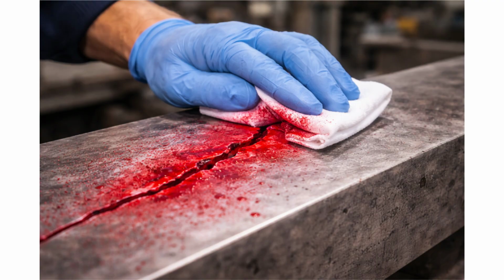Solvent removable. The dye penetrant solvent removable method is most popular because it is low cost and very versatile. You use a clean cloth lightly dampened with solvent to wipe away excess penetrant. The key technique for solvent removal is to use a clean cloth for each wipe. You are not trying to scrub the surface clean, you're gently removing the excess while leaving the penetrant in the cracks undisturbed. If you are too aggressive, you'll pull penetrant out of the defects. If you're not thorough enough, the background will be too red, and you won't see indications clearly. This step requires skill and experience.